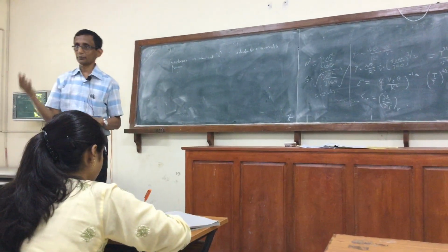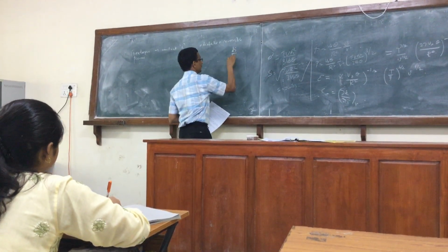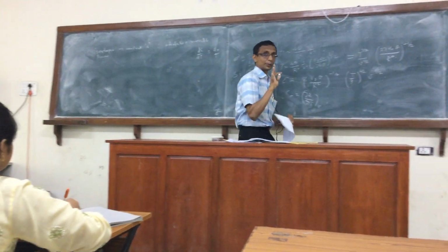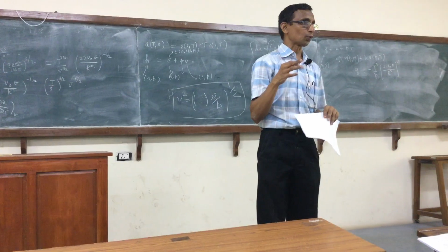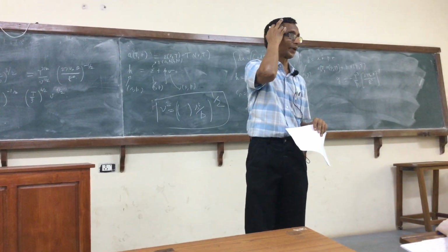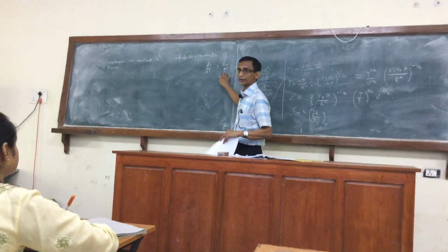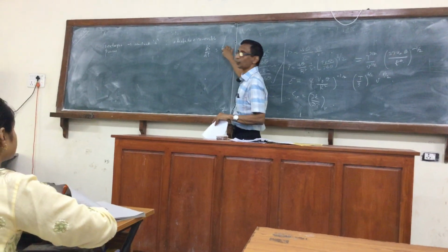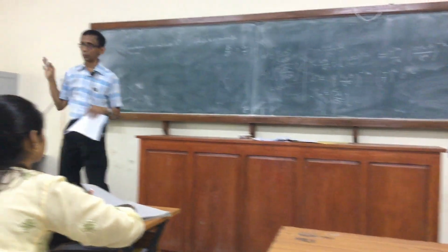We all know that, because the expression dS by dt is QR by T, that's valid only for reversible processes. We have seen, otherwise you have the inequality. So we cannot conclude whether it will be isentropic. If the process is adiabatic and reversible, then this expression holds. So if Q is 0, dS by dt is 0, so the process is isentropic, very easy to prove.